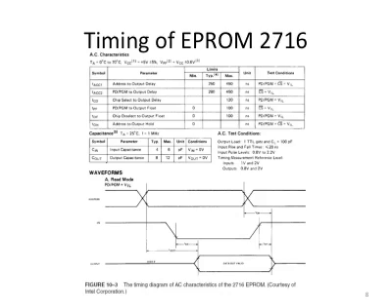So as part of your design, it is safe to assume that after this 120 nanosecond, you will have valid data on the data bus. But it is not safe to assume that after, say, 90 nanosecond, you will see the valid data. Okay? So for designs that you have multiple chips operating at different frequency, you have to be careful whether the action of the next chip can tolerate or can anticipate this maximum delay.